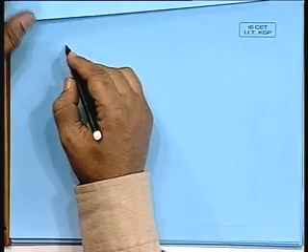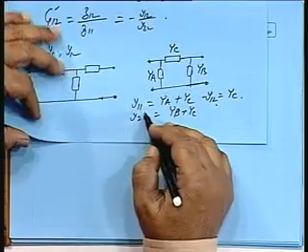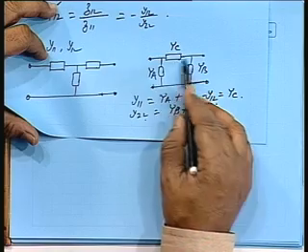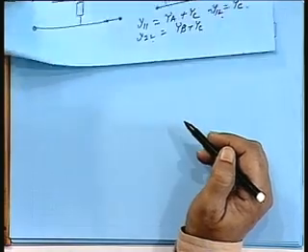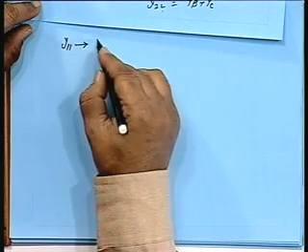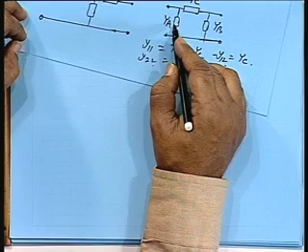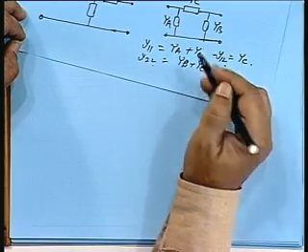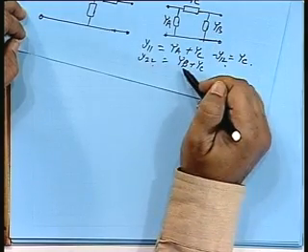In Y11 there can be some poles of YA which are not included in the other two functions. So, poles of YA will be present only in Y11, nowhere else. Similarly, poles of YB will be present only in Y22.